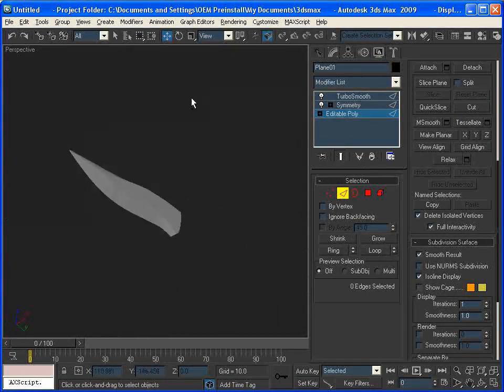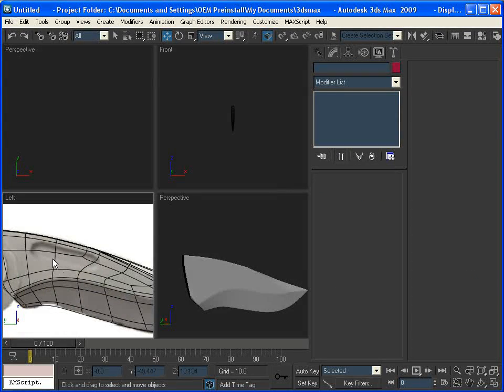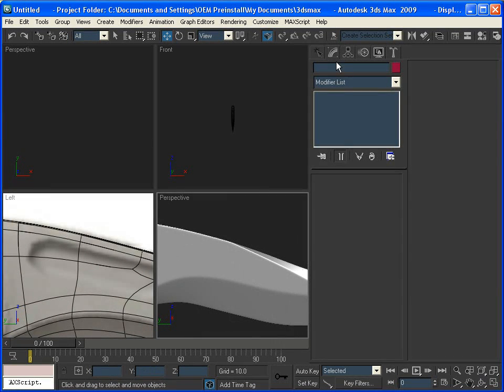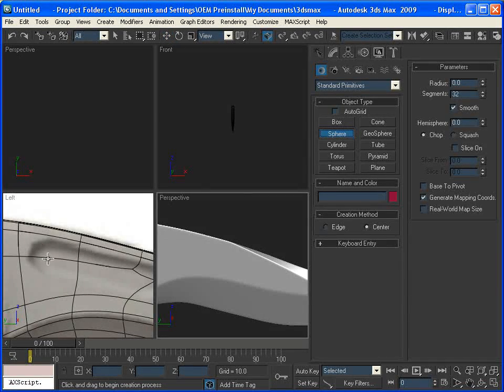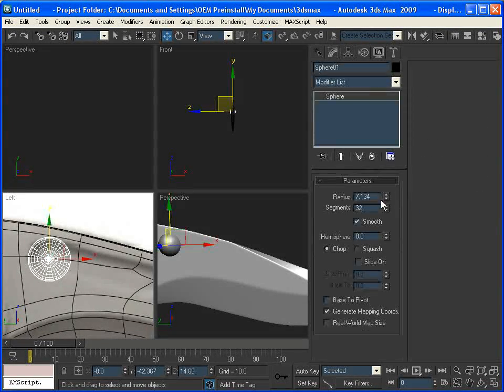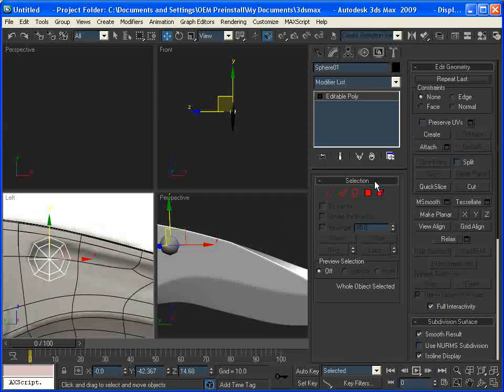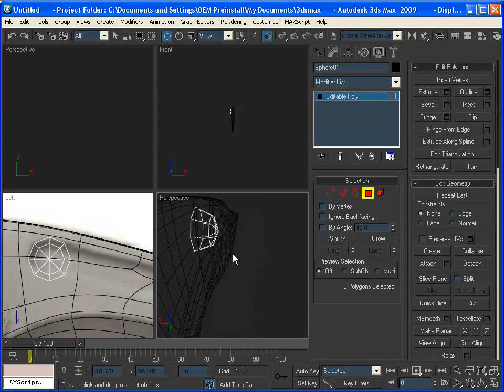Yep, alright, so there's our blade, but there's still something we haven't done with it yet, and that is this indent here. And we are going to do that indent, but we're not going to actually cut it into this surface. To save time, we're going to use what's called floating geometry. Floating geometry is when you take your detail, and instead of actually cutting it in and attaching it to the surface that it's on, you instead just hover it, float it slightly over that surface. And the advantage there is obviously you save time because you don't have to actually cut it in.